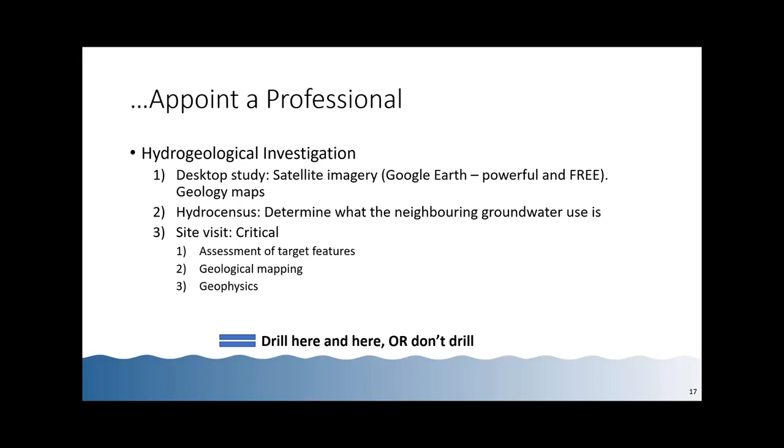And just from step 1 and 2 already, we know that if you drill on, for example, a shale, similar to what your neighbor has, you can get similar results. You'll probably have an average yielding borehole with poor quality. Then you know if that poor quality is not good enough for my use, I want to use it in my house for drinking, I'm probably going to have to treat it. So even before drilling, you know what to expect.